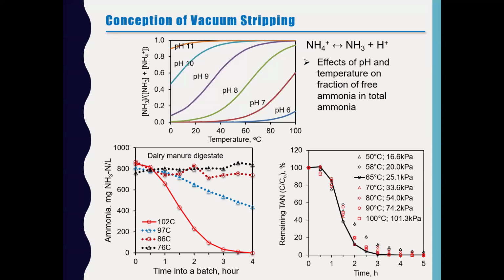That was surprising because we realized the removal mechanisms are different. If not boiling, ammonia is removed basically by diffusion through the small liquid surface area. But if it's boiling, vapor bubbles form naturally in the water. That means a larger interface for ammonia transfer from water to air bubbles, so overall it's more efficient.